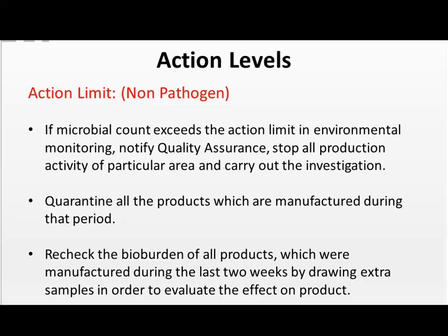If you have a terminally sterilized product, then you can perhaps justify continuing the manufacturing because your autoclaves are going to catch that, but there does have to be tests done to prove that, and typically manufacturing will be halted, products will be quarantined and tested to make sure there was no bioburden in those products.